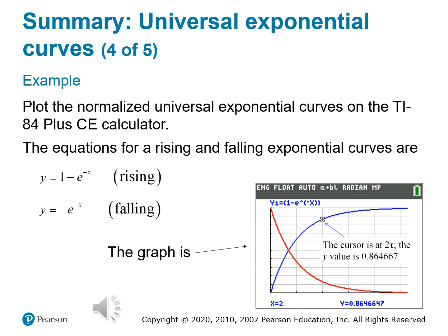This tells you that in an RL circuit, after 2 tau, or 2 time constants, the current or voltage across the resistor has reached about 86% of its final steady state value. The inductor voltage, if you're watching that, has fallen to 14%. Now again, remember that whatever is falling and whatever is rising, both of those at any point have to equal 100%.